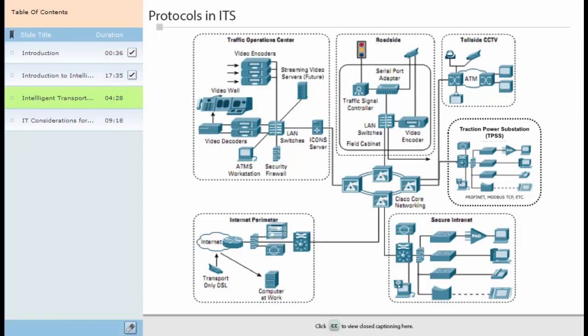Intelligent transportation systems are implemented using a wide range of network components. However, devices connected to the network are typically connected through RS-232, RS-422 or RS-485 serial ports. Devices that require such ports include traffic signal controllers, camera controls, video encoders, decoders, loop detectors, ramp meters, queue detectors, variable message signs, lane control signals, pavement sensors, vehicle detectors, side scan radar, and smart tag readers. Modbus and TCP/IP protocols are also used to connect different devices to the control center.